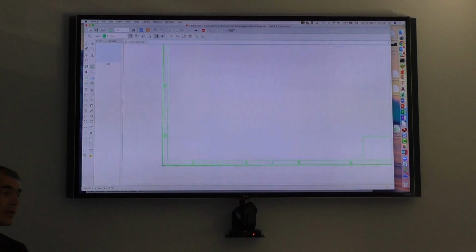I also recommend to work in a proper style: place this frame on the origin, name components in a way that it makes sense, and also name nets if it's necessary. It's much better and better readable also in the layout if somebody has to look into the board.